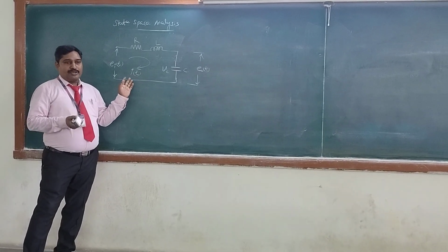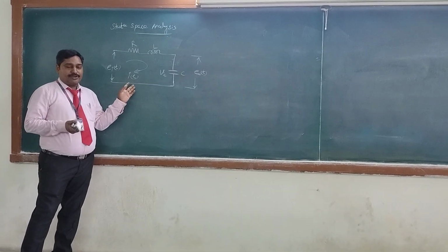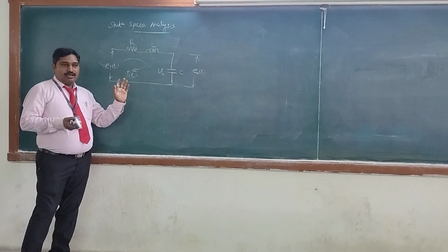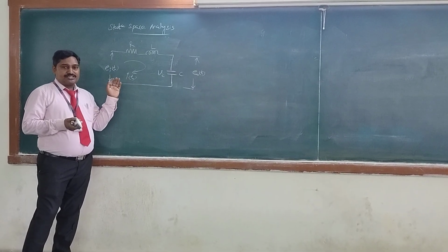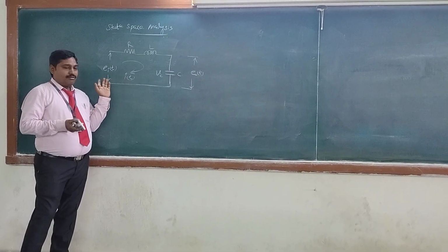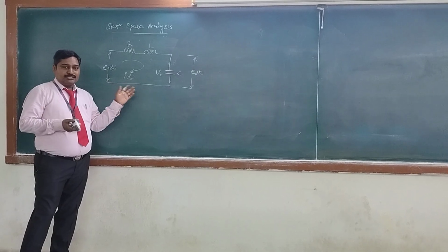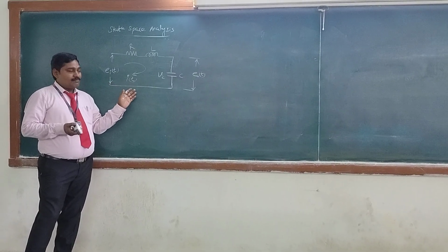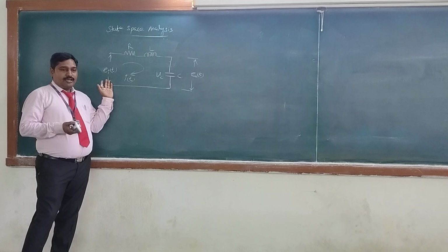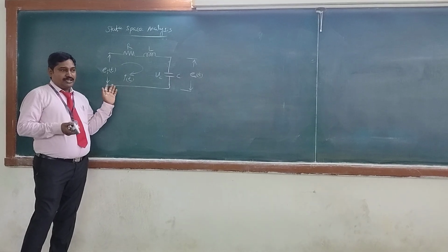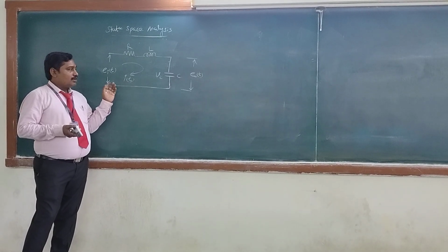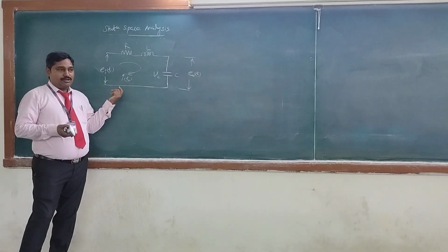Now, how to obtain the state-based model of this network? By applying basic laws, that is Kirchhoff's law and Ohm's law, write the network equation, then select the state variables, then finally obtain the state-based model. So, how do you choose the state variables?